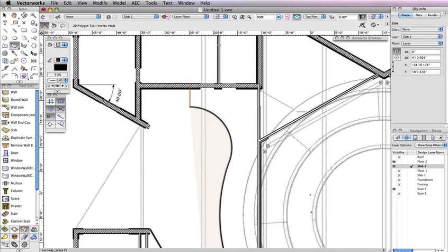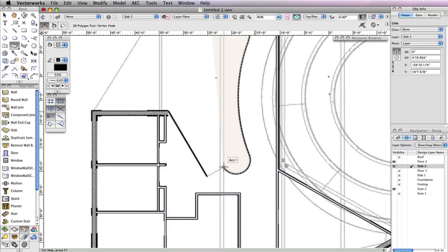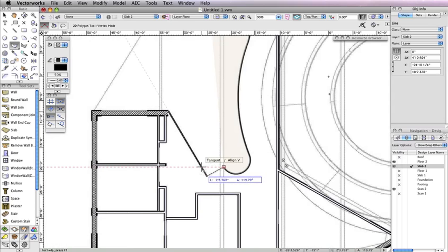With the Polygon tool still active, click on the bottommost endpoint of the curved polygon, and then follow the straight line that is connected to the curve in the scan layer. After the cursor cue, 30 degrees appears. Click somewhere near the end point of the line to match the scanned layer. Now, double-click the inside endpoint of the wall located to the top left of your current point.